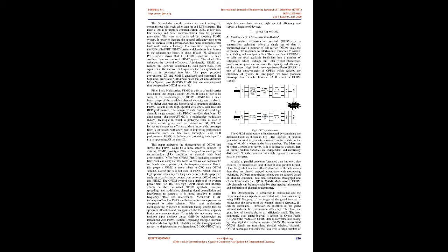All these requirements can be achieved by introducing channel impairments or mitigated by using equalization methods. Performance of the system has been tested for different techniques such as zero forcing, ZF, minimum mean square error, MMSE, and maximum likelihood, ML. Equalization methods are used to compensate for ISI created by multipath channels [5 to 6].